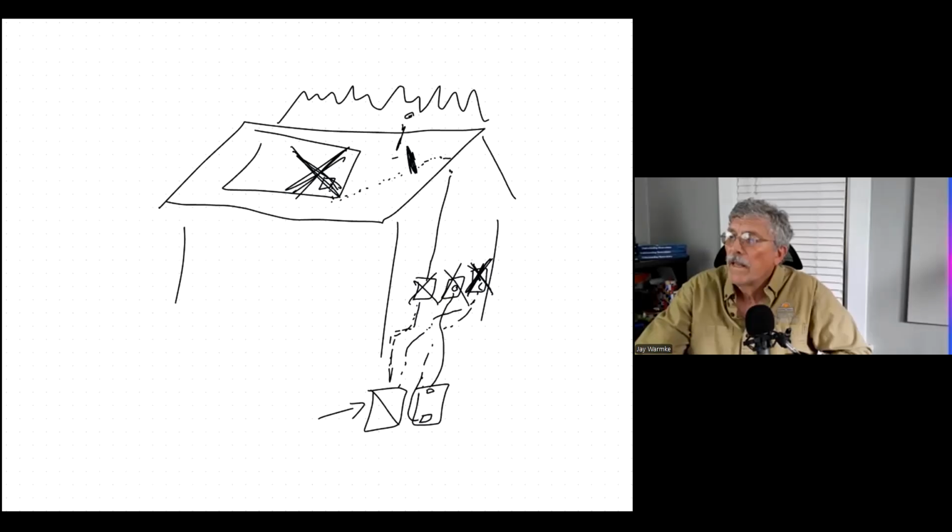So what somebody came up with initially was, well, tell you what, instead of putting the inverter here, let's put it right up next to the array. Well, on a regular residential house, that's not going to work because you've got this 100-pound piece of equipment sticking up there. But on top of Walmart or on a flat roof, yeah, that'll work just fine. You can set the inverter right next to the array because they didn't actually say at the array.